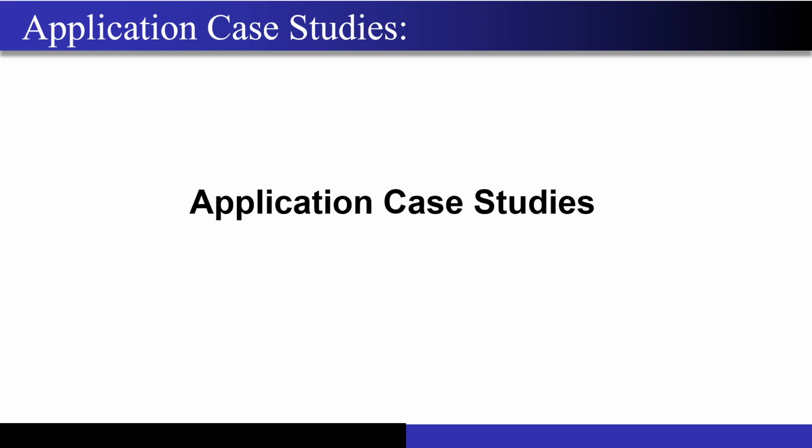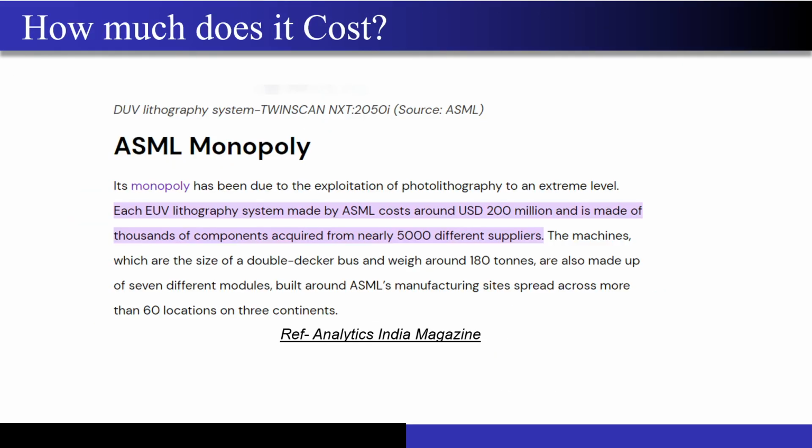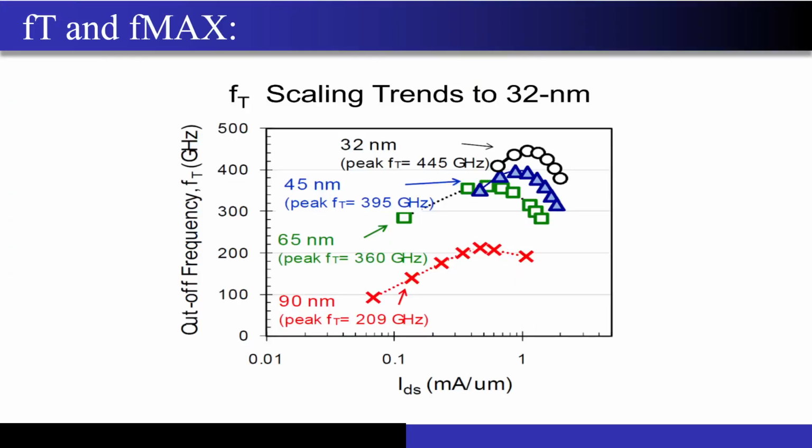Yeah, so it actually depends on the application. If you want to design an amplifier where you don't need a lot of swing out of that amplifier, then you may be able to live with a 0.9 volt supply voltage. It is absolutely no problem. But if you want a very good gain amplifier which has very high speed as well as high swing at the output, then according to the swing you have to first decide where to go. The supply voltage should not be so low that I will not be able to get any swing out of the amplifier. Just give me a second.